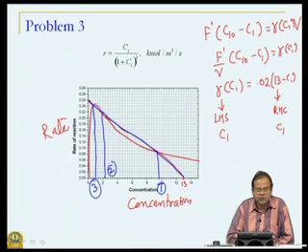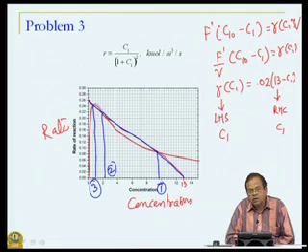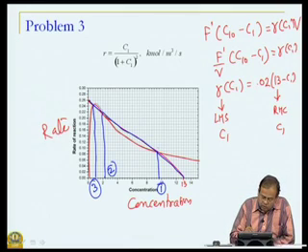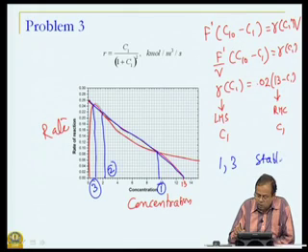If you look at left hand side, it is nothing but mass generation or rate of mass conversion or the rate of reaction, and the right hand side is nothing but mass in and out, net mass added to the system or removed from the system, whichever way we want to look, and the steady state is a balance between the two, which is what we expect. So, based on the discussions that we had, we can safely say, and you can verify it, that 1 and 3 are stable and 2 is unstable.